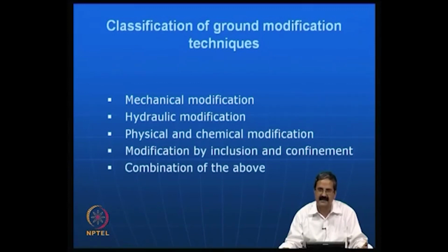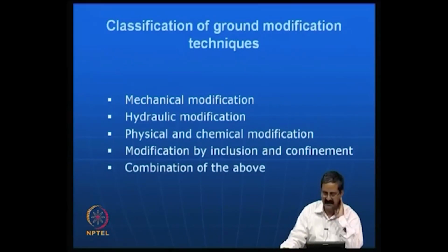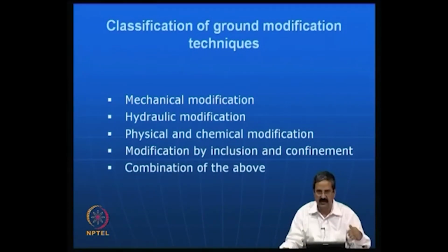The other important point is the confinement effect. Sands do not have any confinement effect, in the sense that sand has negligible cohesion, right, and a friction angle of, say, 30 degrees. I want to increase the cohesion in sand. I can use reinforcement or geocells, which we will see, and one can improve the ground using these inclusions or confinement effects, either in the form of reinforcement like geogrids or confinement using geocells.